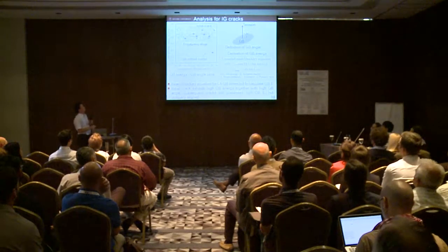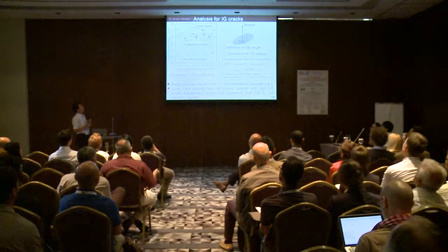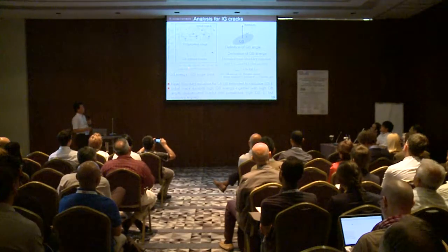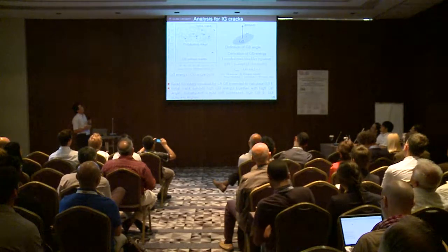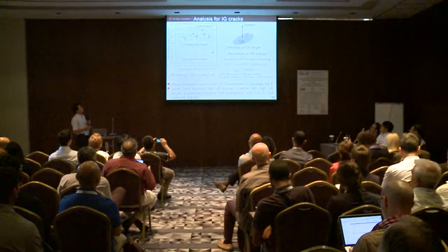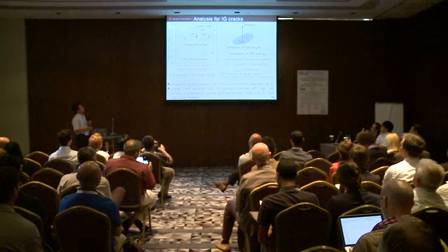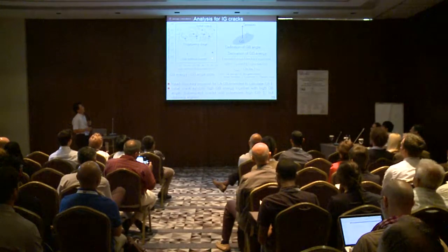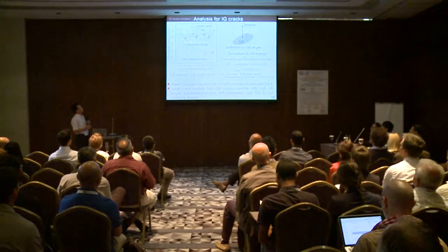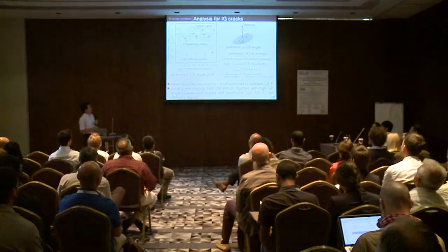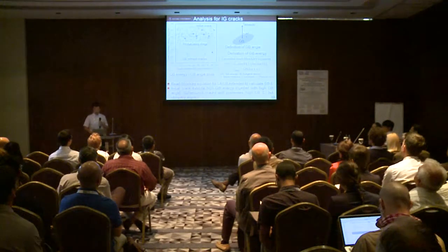Then these are intergranular cracks. We are looking at grain boundary energy as a function of grain angle with respect to the loading direction. And you can see that the initial crack has fairly high grain boundary energy, which is almost perpendicular to the loading axis, and then it propagated, spreading through grain boundary planes with relatively high grain boundary energies. So this is a mechanism of intergranular crack.